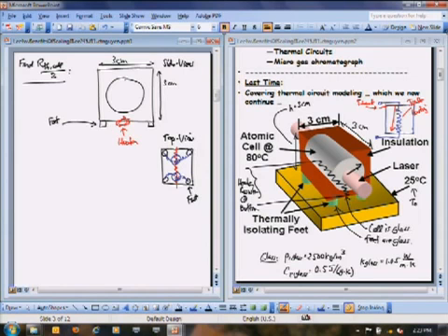Okay, so what am I going to do? I'm not going to split this into 2 currents. I'm going to call this one current source like I did in the circuit from last time, right? And I'm just going to say that I want the resistance from this point to that point. Not electrical resistance, we're talking thermal resistance. Right, so this is my R_TH of the cell over 2. Okay, that's what I want to do. Okay, so how am I going to go about doing that?